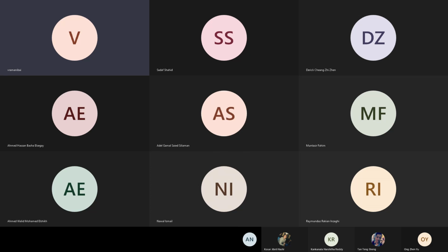A member can be either loaded by a load or by directly applying the moment. By that, the section design will be changing. In the first case, it was about a length of, I don't remember the values, but 0.3 on both sides and the middle had some values. But the same member can be changed to a smaller length with just applying the equivalent load as the equivalent moment, the couple moment, moment couple at both ends, by calculating the moments caused by the distance and the loading. So this is the other way of loading the member or designing the member for this situation.